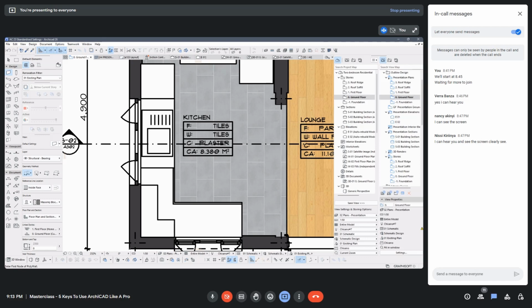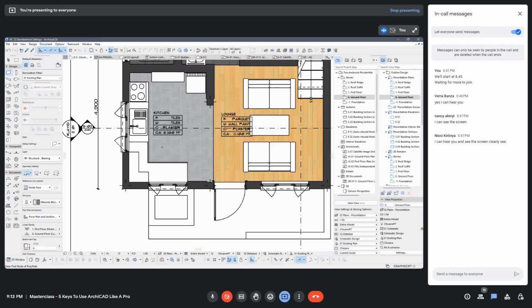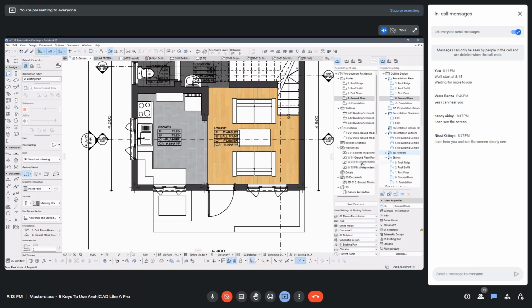So that's why I'd choose a schematic model view option. And I go to detail. Now I know it's casement window, and it's double hung, so this is hung on one side and the other side. So as I'm moving forward, ArchiCAD gives me the ability to choose the detail level of my elements. So that's that on model view options.